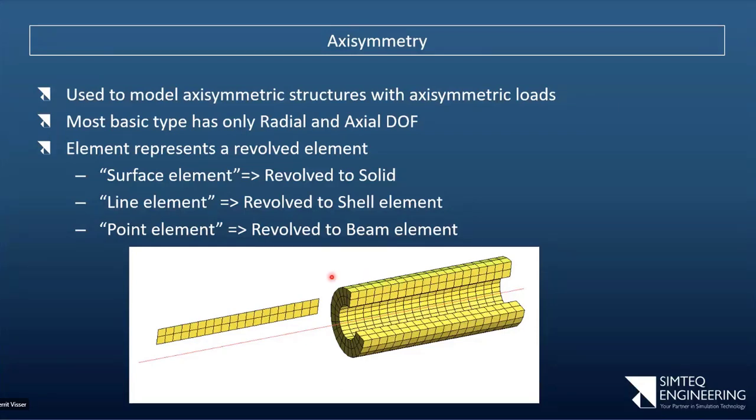So there's a strain in that direction. So the minimum constraint that you need to apply for the model to run, I'm not talking about accuracy, just to be able to run, would be a constraint in that direction. If I look at all the previous elements, the plane stress, plane strain, and generalized plane strain, I needed a constraint in the X, the Y, and some way to stop the rotation about the Z direction by constraining, argument's sake, two nodes with a moment arm in X or Y direction.